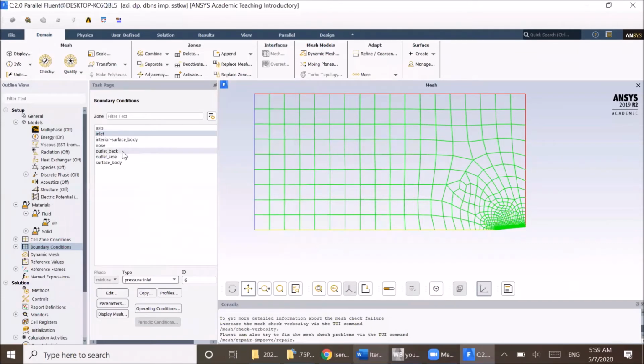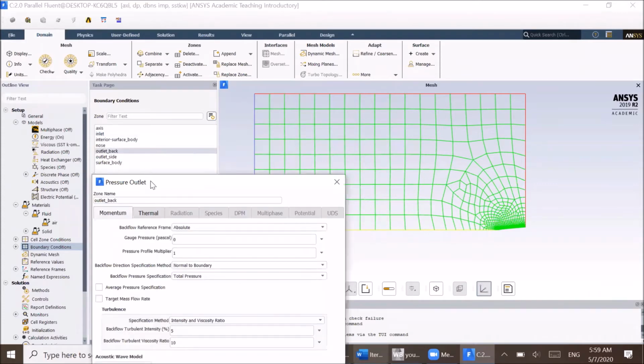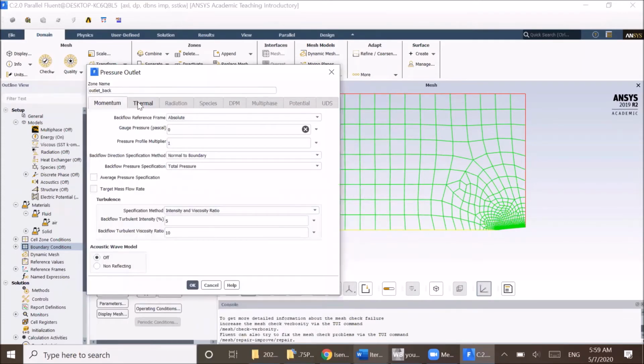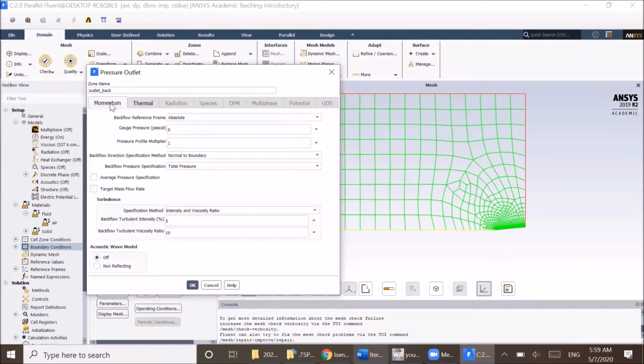All right. Now we also have to change our pressure outlet options. So our temperature is going to be the same one we calculated for the pressure inlet option. And for the backflow direction, you want to make sure you have that selected to from neighboring cell.